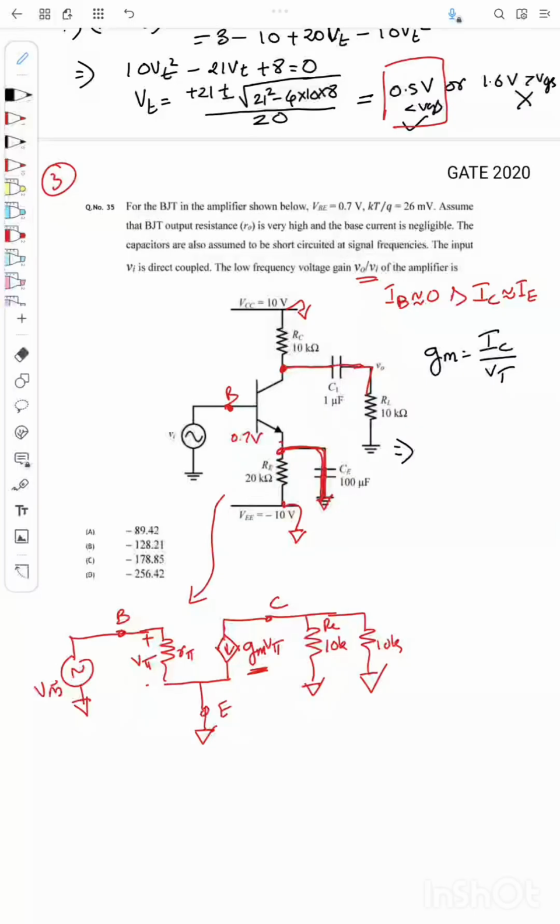We will replace the signal with frequency with its equivalent circuit resistance, that is, we will short circuit the voltage sources and open circuit the current sources that carry the signal. So here I will connect only the DC value.